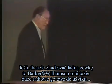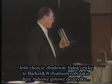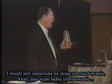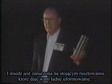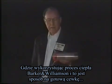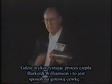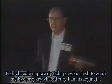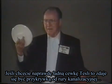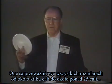Okay, if you want to build a nice coil, Barker Williams makes a large variety of these coils ready-made, and they're copper and they've been dipped in stannous chloride, which tin plates them, and that's how you get the pretty tin plate. They've used a heat process to embed them in slits of Lexan, and that's what the ribs are made out of. Now, if you want to make a real pretty Tesla coil, this happens to be the cap off of a sewer pipe, and they come in all sizes from about a couple of inches and a half up to over 25 inches.